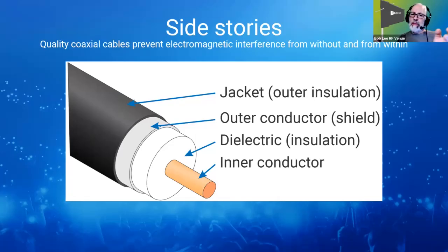Always use 50 ohm cable. Don't use 75 ohm cable, because that's for TV and video systems, CCTV, cable TV, so on. It will not work well for wireless RF systems because you'll have an impedance mismatch that will cause reflections and uneven frequency response, stuff like that. So use good quality 50 ohm cable.